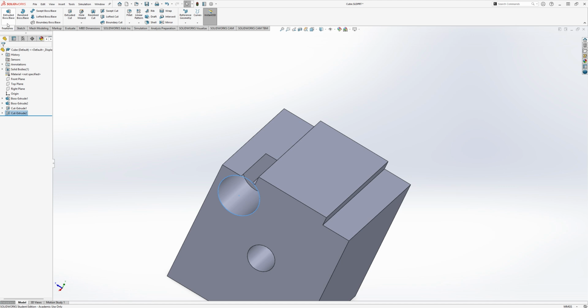The next thing we're going to look at is a fillet here. So when you click this down arrow you'll have two options. You'll have fillet and a chamfer. Both do the same thing slightly differently. A chamfer will add a straight edge to your angles such as this line here, the orange one that I'm showing. You'll add a straight edge, whereas the fillet will add a radius to it.